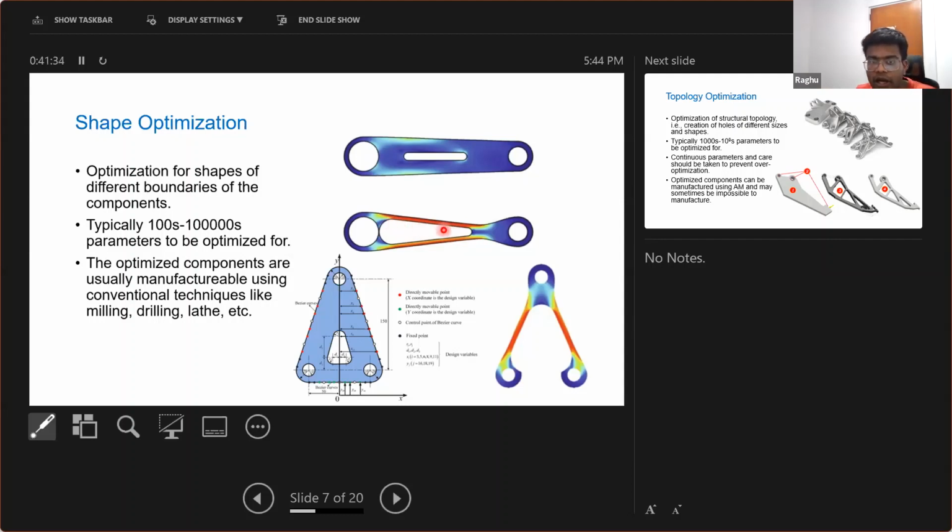So the contours, the colors on these pictures, indicate the stress values. If you see, the initial solution has very little stress as compared to the final solution. However, you should make sure when specifying the constraints that this maximum stress which is happening here is still within agreeable limits, which is chosen completely by you based on the application you're going to use this wrench for.